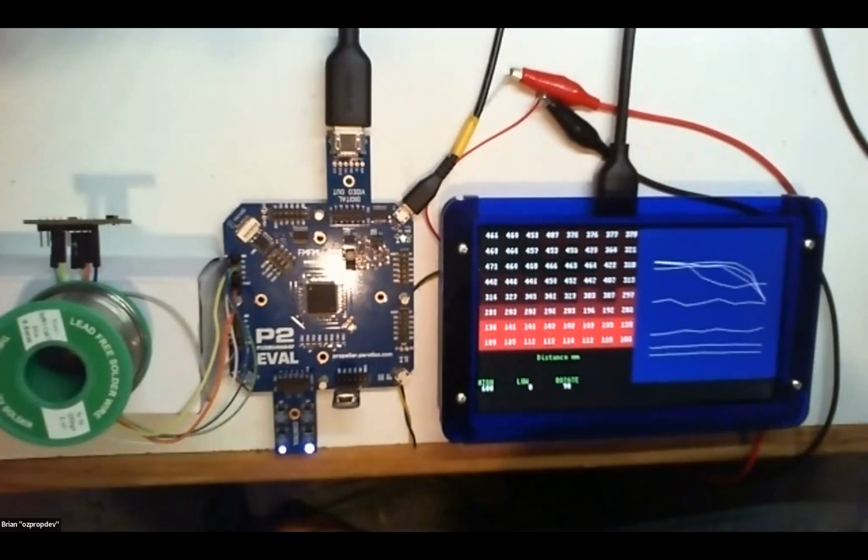It does have a 4x4 mode, which you can take up to a 60 hertz refresh rate. So if you want to drop the number of zones, or the resolution, and get your refresh rate higher, you can just drop down to the 4x4 mode. For the drivers that run this, ST Microelectronics have a C library, which has all the bits and pieces you need to get the sensor going.